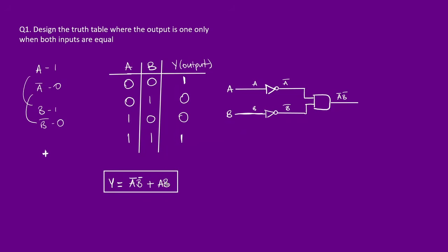We carry on with this, and we need to make the second half, A and B. What is this? AB is the AND gate. Remember we said that it's A and B, but it will usually be represented as straight up AB. So we'll need to do AND AB again without the negation. How this is done is pretty cool actually. You draw lines from A. So you can bring this here. You draw lines from B. You can bring this here.